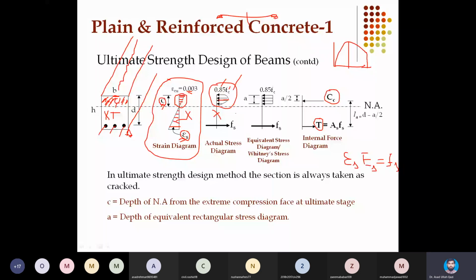If I can replace this with a simplified uniform stress block with the condition that from both pictures I will get the same amount of Cc, and from both pictures I will get the same point of application of the resultant Cc, if I can prove both, then this simplified right side picture will be more preferred, because it is much easier to calculate Cc from this.